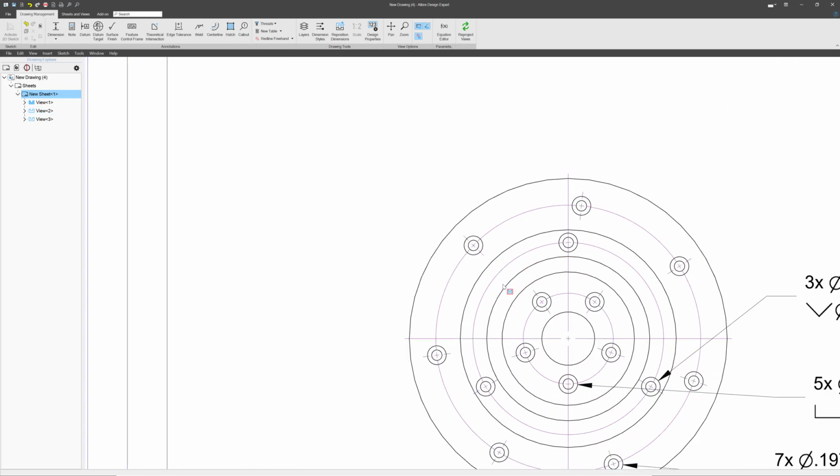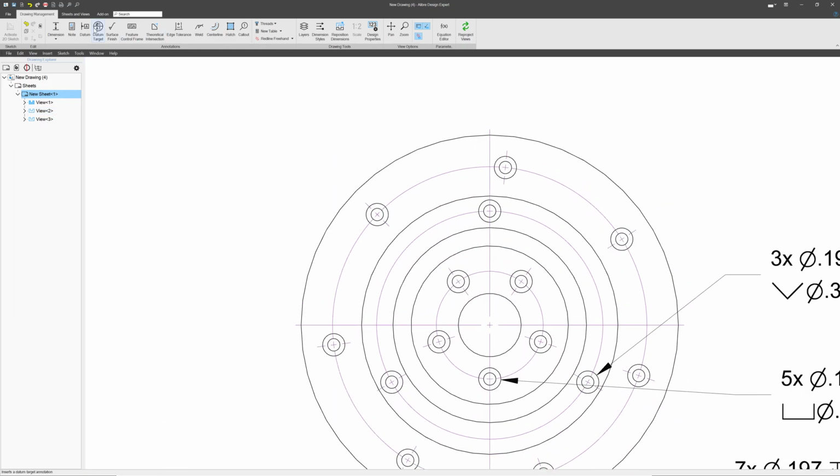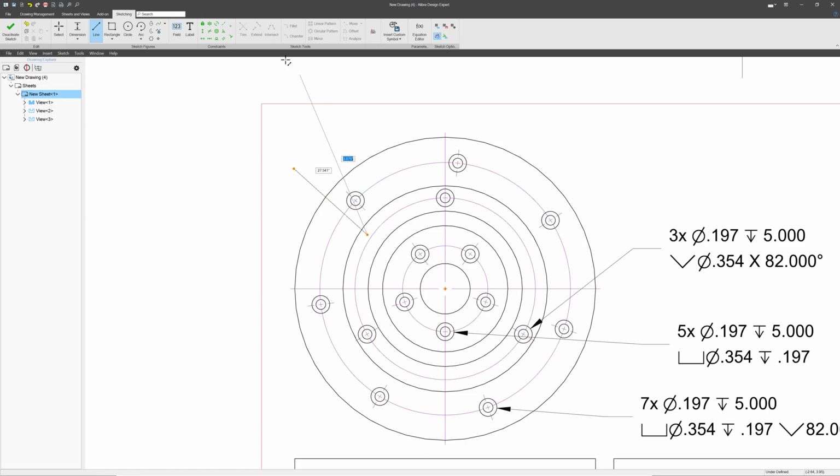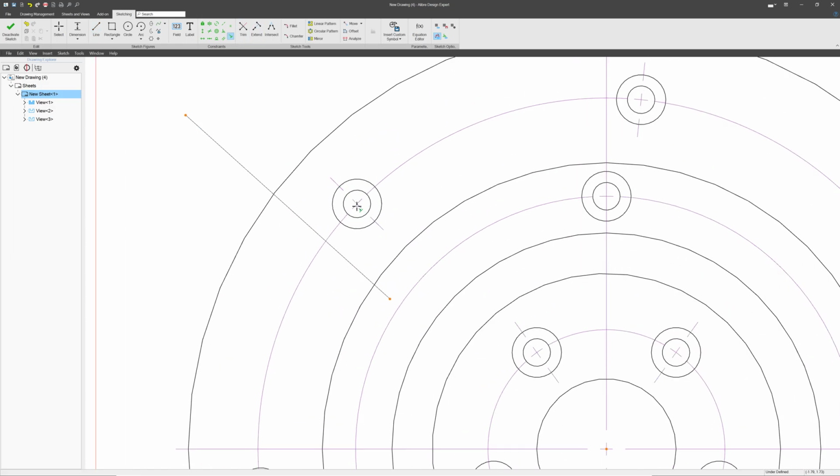But how do we section view these holes if I wish to have a section view with all of them? Well, it's easier than trying to make 3 different section views. We could save a lot more space simply by, again, starting a sketch. And I have my coincident here, so I can make my line coincident on my hole, just like that. I can also use a point and make it concentric with my hole. That's one of several ways to do it, but that's my personal favorite because now I can reference the center of my hole. Again, many ways to do the same thing in CAD.